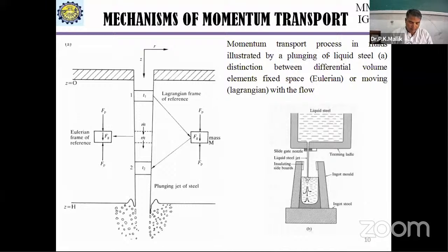Most are the law of conservation of mass, or the continuity equation; Newton's second law of motion, or the momentum theorem; and the first law of thermodynamics, the energy equation. These are the basic equations. If you utilize these equations with mathematical, mainly differential, derivations, you can solve most of our problems.